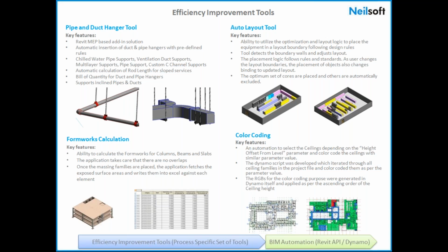that is where automation helps in implementing this, where we can insert these pipe hangers or duct hangers in an automated way, where within a few clicks we can have hundreds or even more hangers placed within the model, and we can build intelligence into it where it can recognize what the pipe size is, what the insulation thickness is, or what the size of the duct is, and based on that it can modify the hanger instance and place it using design rules or specifications that are required. And that greatly reduces the design time that's required, improving the efficiency.